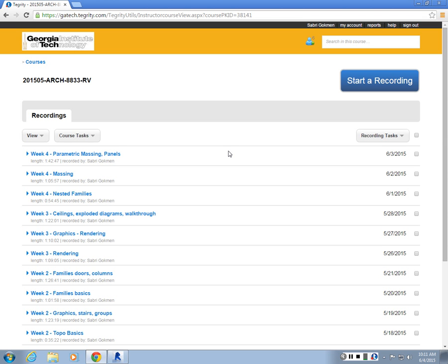And then this profile geometry will still undulate because they are hosted by these points, right? So they are controlled by these points. And then if I have an earth surface, and if I have control points here, which need to correspond somehow to that, so I have, let's say, 4 rows of control points, and these are actually going in this way, so there's like division. Then I come in here, use the adaptive component, and then place it in this order.